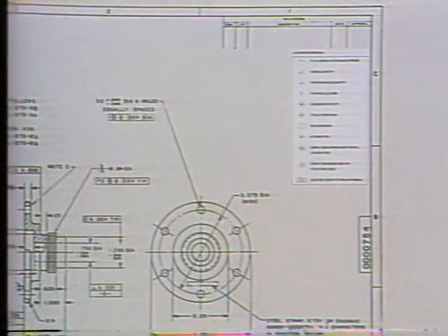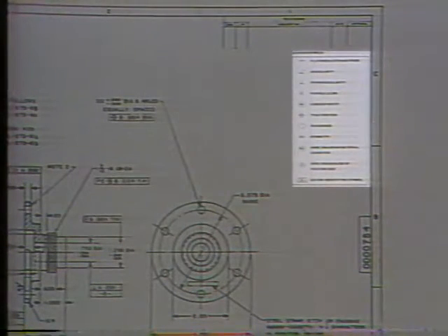Anytime you discuss the assembly, disassembly, or maintenance of a machine, you have to be aware of a key area. That is, you have to be able to recognize and understand the different methods used to fasten parts of a machine together. If you don't recognize and understand the various fasteners, you're going to have a difficult time assembling or disassembling a machine. Now, a word of warning here. There is a tremendous variation in the methods used by different manufacturers to represent a part or a machine in a machine print. Just as you did for piping prints and for fluid power prints, you need the manufacturer's legend for any machine print you use.